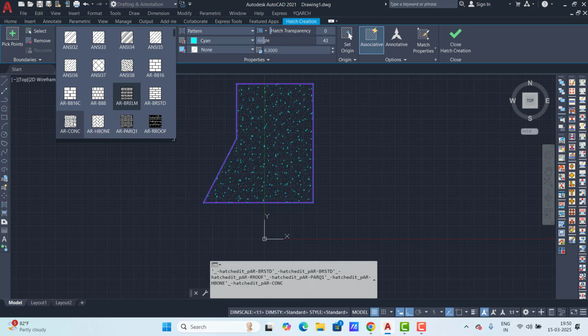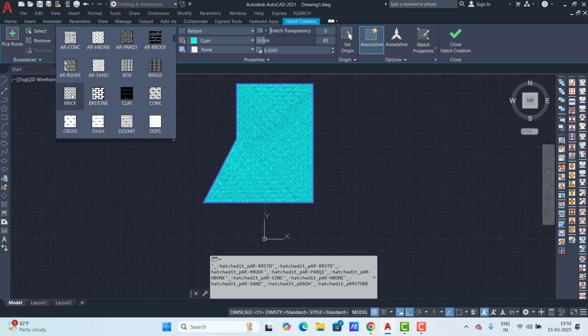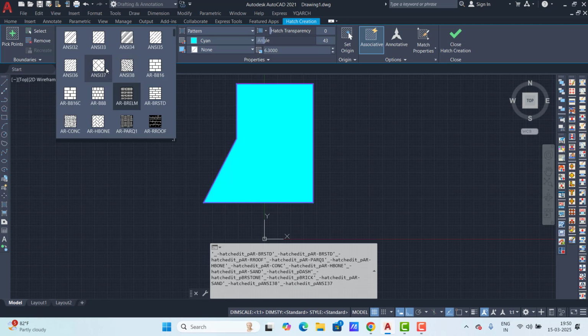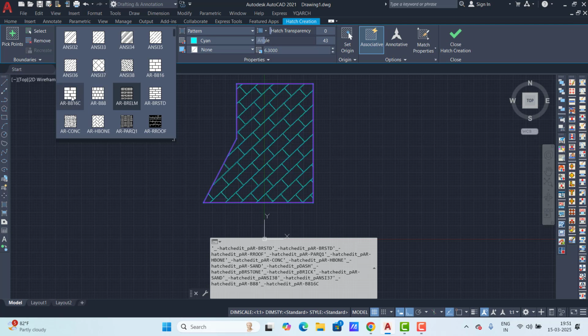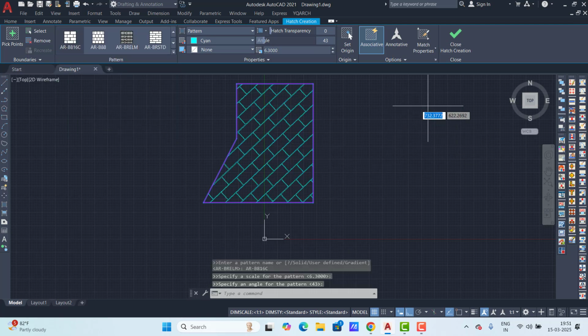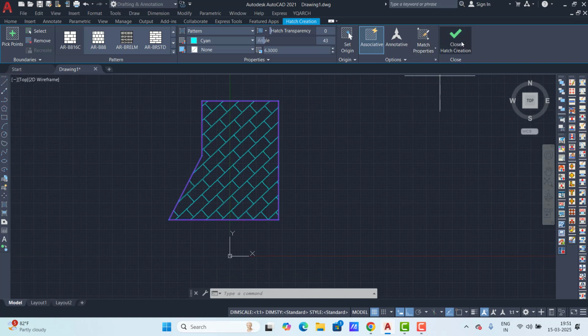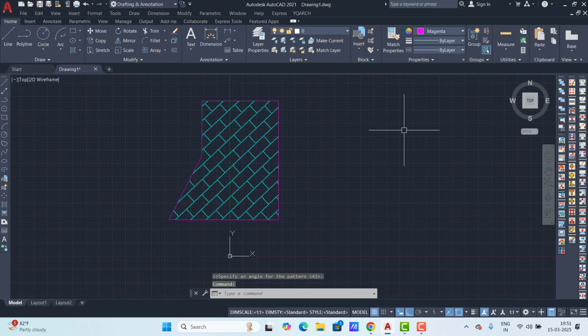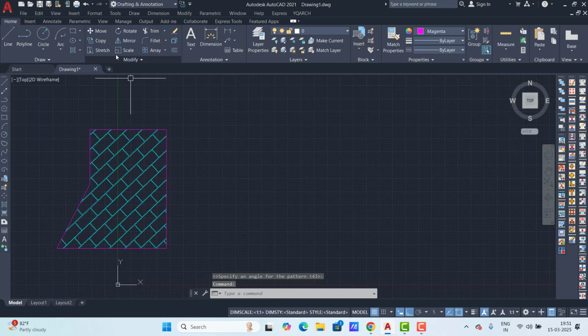You don't know the boundary option. So what does the boundary option do? The boundary option just follows this boundary and creates the same object, a duplicate object on top, and it comes in polyline form. So before teaching boundary, let me explain one more option, region. That is REG, enter.